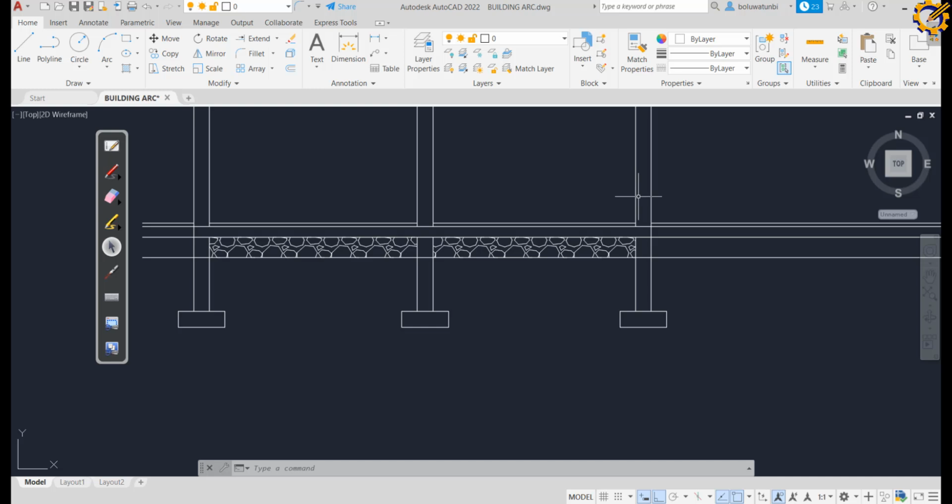And if they are doing the flooring, it is going to cover the entire area that they excavated. Are you getting it? The concrete is going to cover the entire area such that all the walls, all your excavated shape, everything, you won't see anything again. All you will be seeing is what? A flat surface. Are you getting it? So after the floor is now fully dried, then the engineers will bring the building plan and start marking out the positions of the wall again.